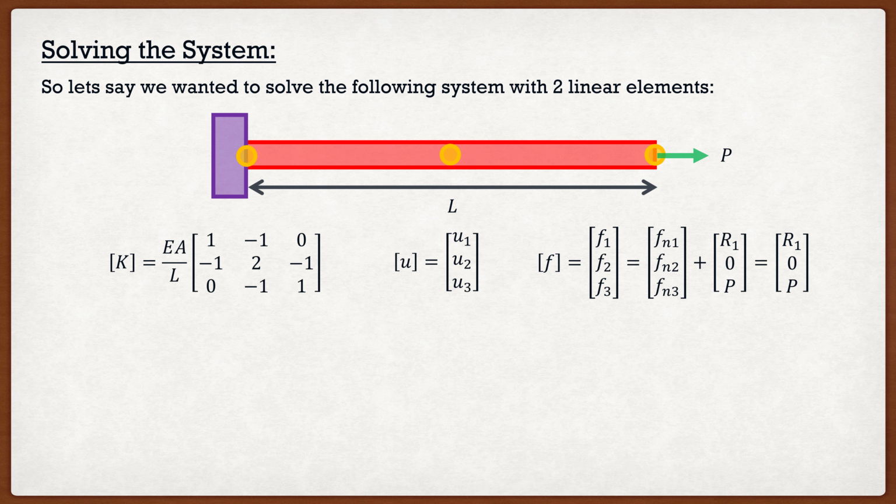Now, our nodal forces vector is actually composed of two things. The first one is the nodal forces vector that we solved for, which came from the integral of P times Ni. What this essentially accounts for is the distributed loads, so these are the loads between the two elements. Our second term, which we talked about before, was related to the concentrated loads applied at each one of the nodes. Remember that in our derivation, we canceled it out because we said we're basically calculating something that's going to be equal to 0 unless a very specific case happens.